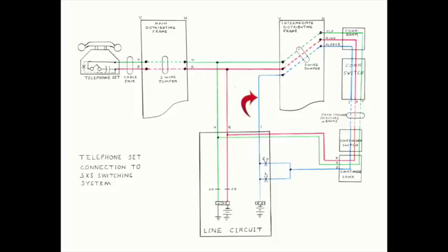One goes to the vertical IDF termination, which has been cross-connected to the telephone number sleeve termination and thus through to the connector bank sleeve termination. The other sleeve lead is cabled directly to the line finder bank sleeve terminal. So let's take a look at the operation of the line relay and the cutoff relay in the line circuit.